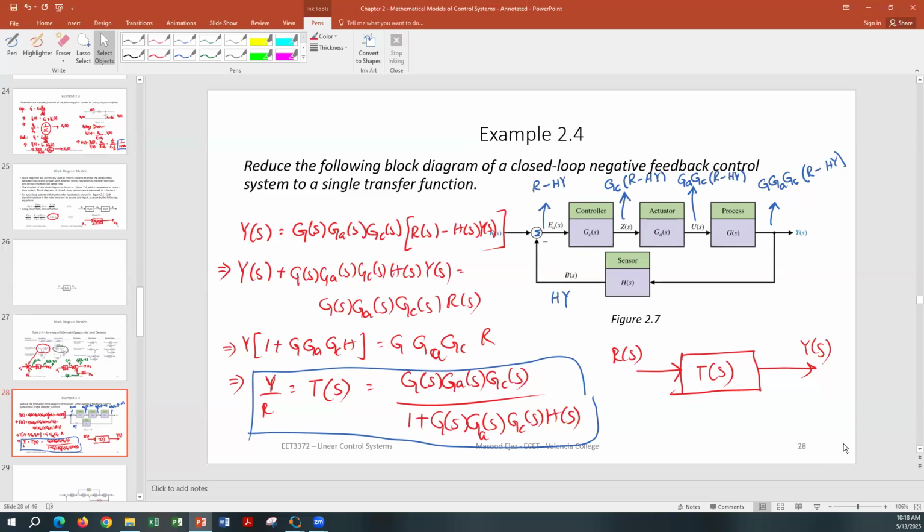Again, that may require you to have 5 capacitors, 3 inductors, whatnot, whatever. So just assuming that this is only a gain of the amplifier may not be a correct assumption, but you can assume that in general it is basically the transfer function or gain of the amplifier. You can call it the gain, but don't assume that it's just one amplifier in there producing a gain. It can be a huge system. Some may be producing gain, some may be attenuating the signal, some may be clipping the signal or whatever.